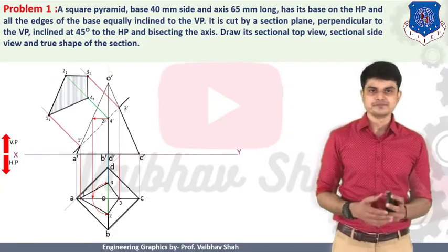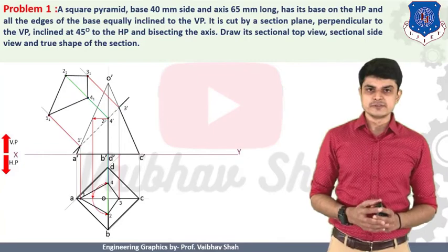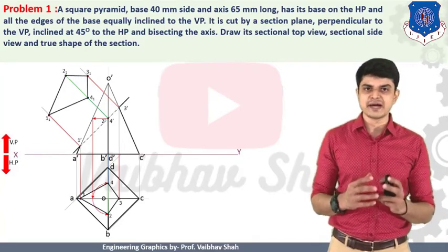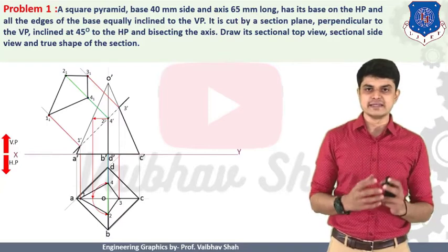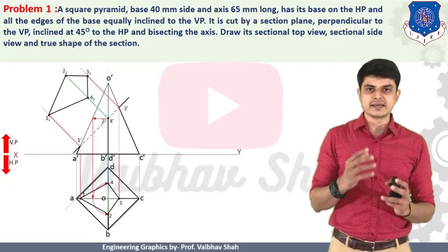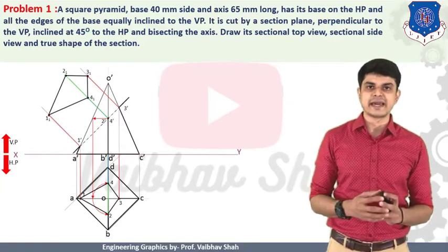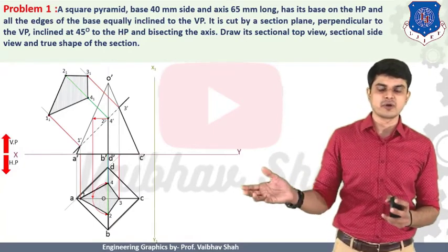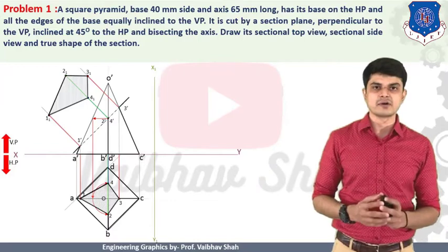Right? Very easy. Now, after getting these views, as these are the section planes, we know that sections are shown by hatching lines at 45 degrees and at equal distance apart. So let us show the hatching lines on the surfaces like this, on this surface as well as our bottom portion. So we'll be having our object generated.